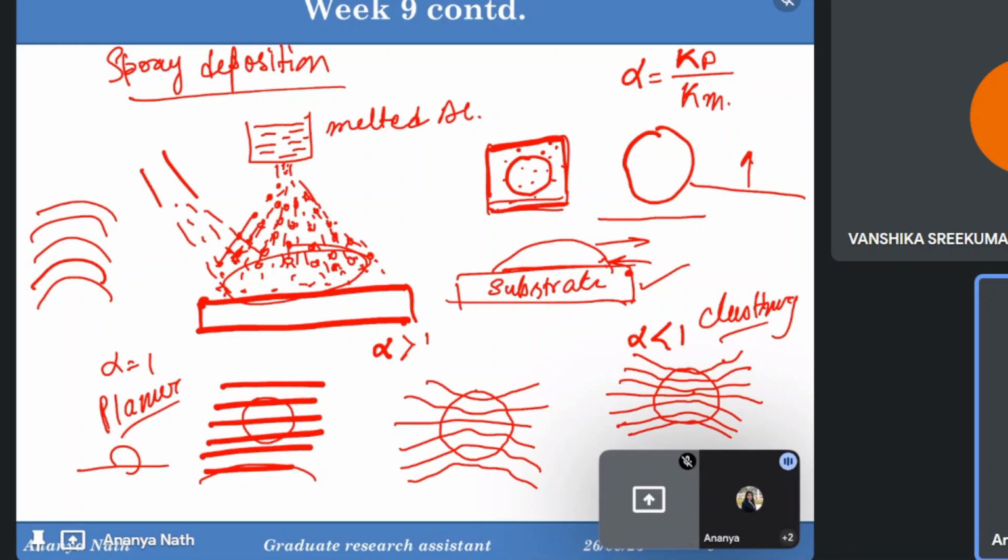But apart from the second phase precipitates formation, there are some other strengthening methods as well. If you can recall the second lecture in week one or the third lecture, somewhere around that, there were the strengthening methods. If you are adding strengthening, it means what? The disruption in the dislocation movement inside the lattice. So strengthening can take place in many ways. Like if you broaden the stacking fault width, the stacking fault energy will be low, and at that time the dislocations cannot move. Strengthening will take place. If you are adding solute atoms which have reverse affinity or electronic configuration in such a way that it makes some dipole inside the material, then the dislocation movements are hampered. That is a kind of strengthening.